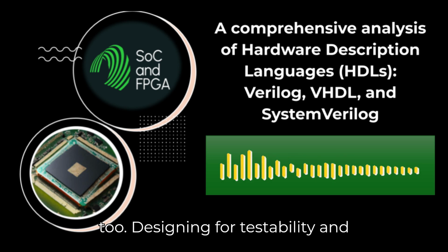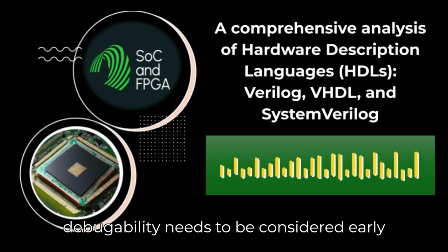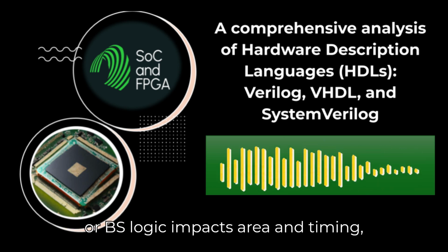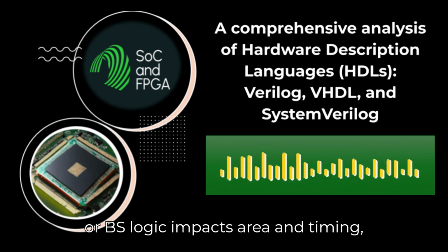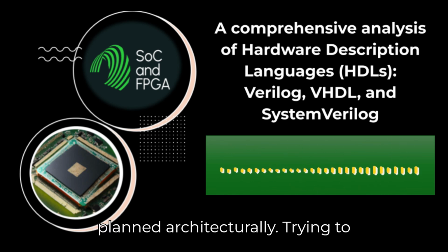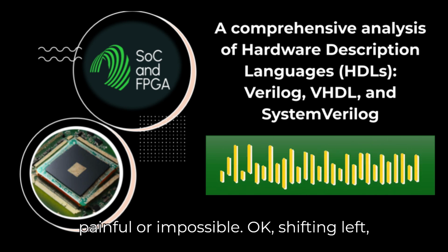Designing for testability and debuggability needs to be considered early in the design cycle. Adding scan chains or BS logic impacts area and timing, and debug access points need to be planned architecturally. Trying to retrofit it late in the game is often painful or impossible.